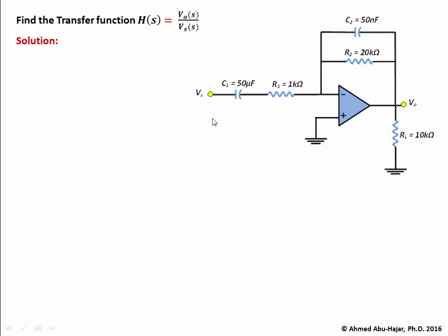And to calculate the gain of the amplifier, the first thing we have to do is to find the impedance of the capacitances C1 and C2. So the capacitor C1, when you convert it to the impedance Z of C1, that will basically equal 1 over S C1. And the capacitance C2, when you convert it to Z of C2, that is basically going to be 1 over SC2.